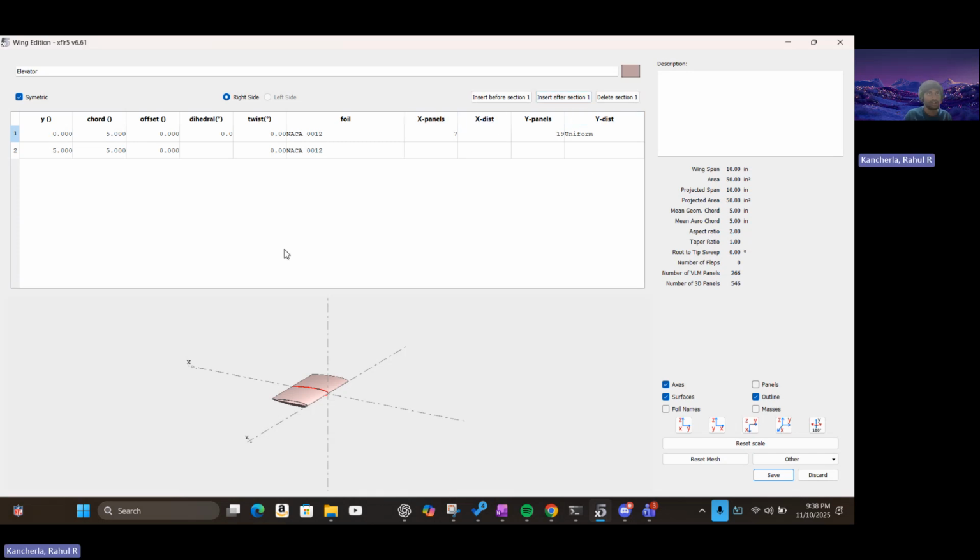Typically, how we determine that is we find a list of airfoils that we think would suit empennage and wing, two separate lists usually, which we get from previous reports, proposals, research, as I said, and then from there we do analyses, testing, and all that, to see which particular shape would actually give us a desired advantage.